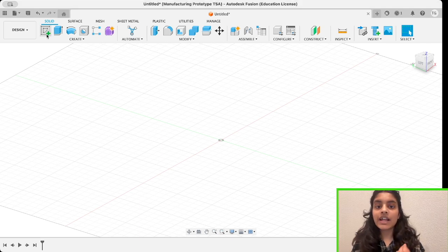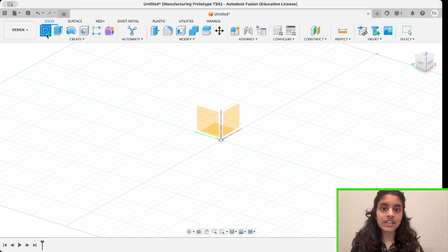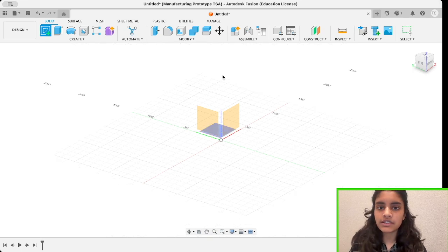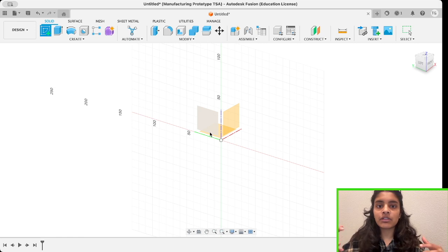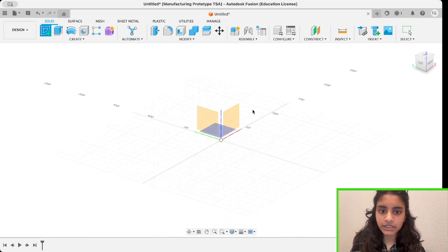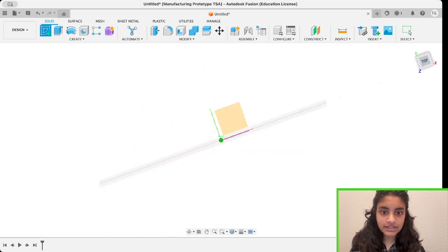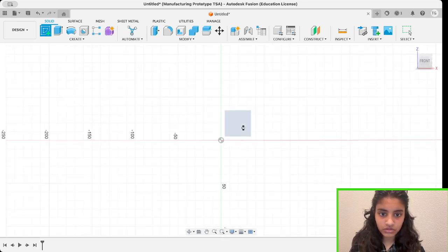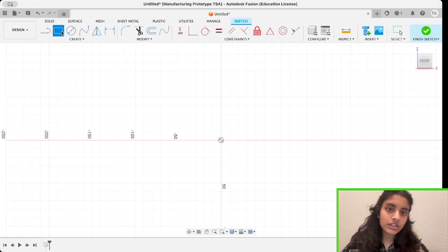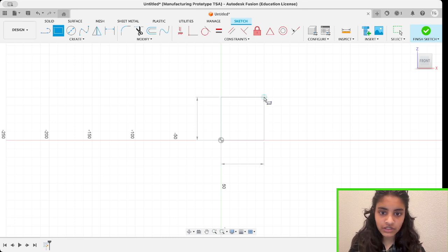So let's get started. Last video, you learned how to create sketches and build your first individual bodies in Fusion 360. Today, we're going to start adding more parts to the projects that you've already learned how to make. So let's say we were creating a new body here in Fusion 360. First you would click Create Sketch, and then choose an axis to do it on. After choosing your axis, you can start creating your basic sketches. Today we're just going to go with the simple rectangle, and you can snap it into place and choose all of your dimensions. So this is just going to be my basic sketch for today.